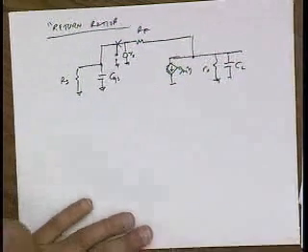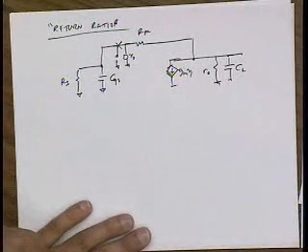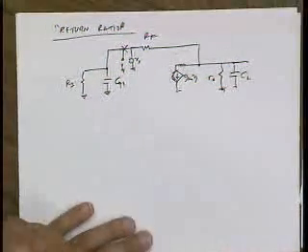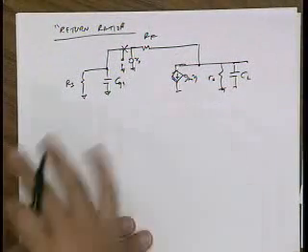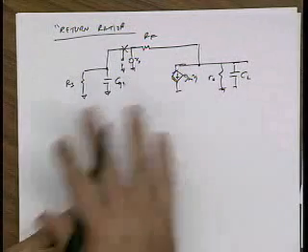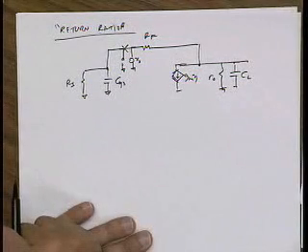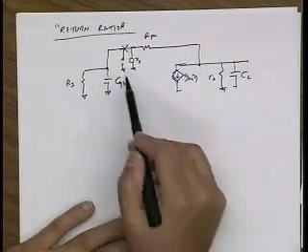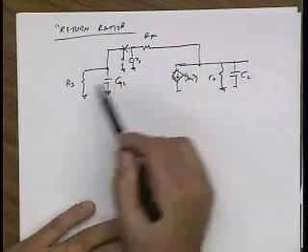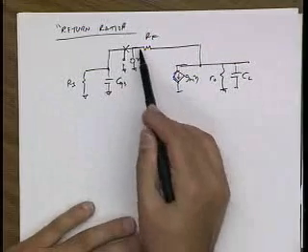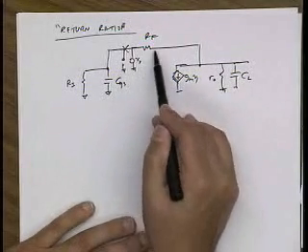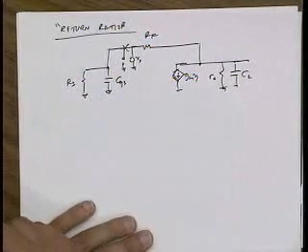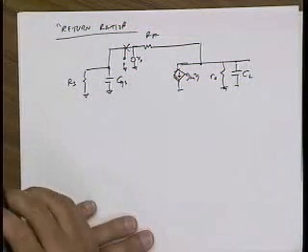Yes? You lose loading effects on RF. Yeah, remember, this is not a signal flow diagram. You can't just do that. There's impedances everywhere, so you don't want to disturb the impedance levels of the circuit. Here RF is loaded by these two impedances, and that has an impact on the loop gain. If I break this point and put a voltage source, effectively it looks like I've shorted RF to ground. Clearly I'm not going to get the right answer.